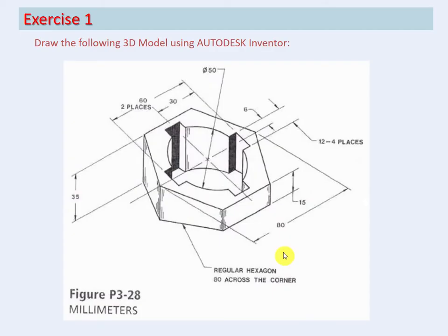Now, we want to cut this surface, or remove from the top some material, to get this slanted surface. We have 2 ways. We may create a work plane here, then draw something like a very large rectangle, and cut or remove the upper material. Or just draw a line here, somewhere here, guys, and make what? Split by trimming the solid.